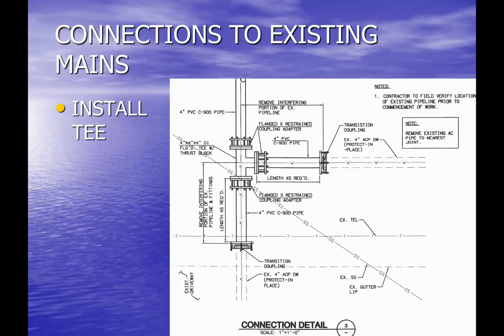So there are times where it makes perfect sense. This exhibit you see was one where we cut out the pipe and installed a brand new T to create that new branch. And that's a very effective way to do it if all the conditions are right.